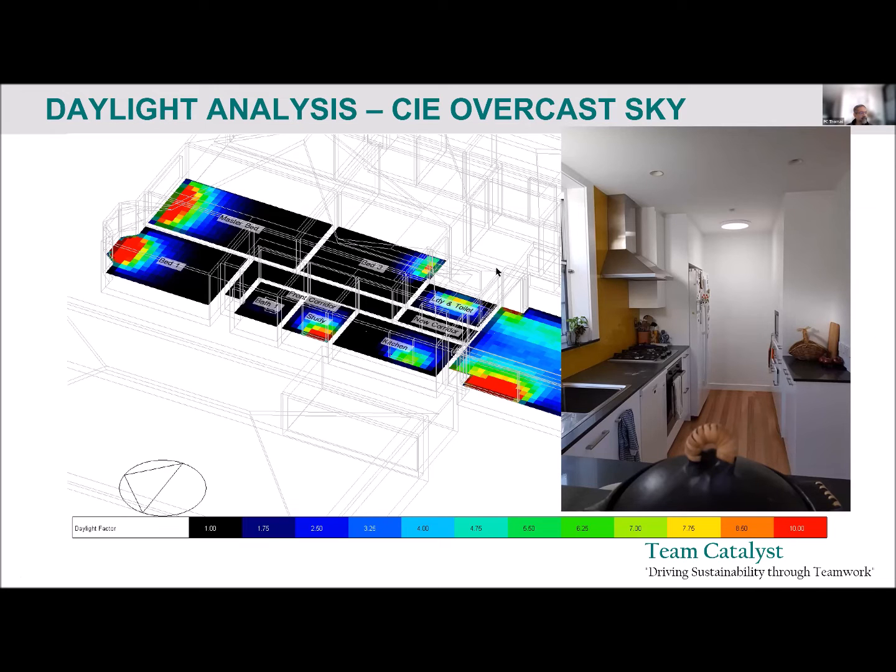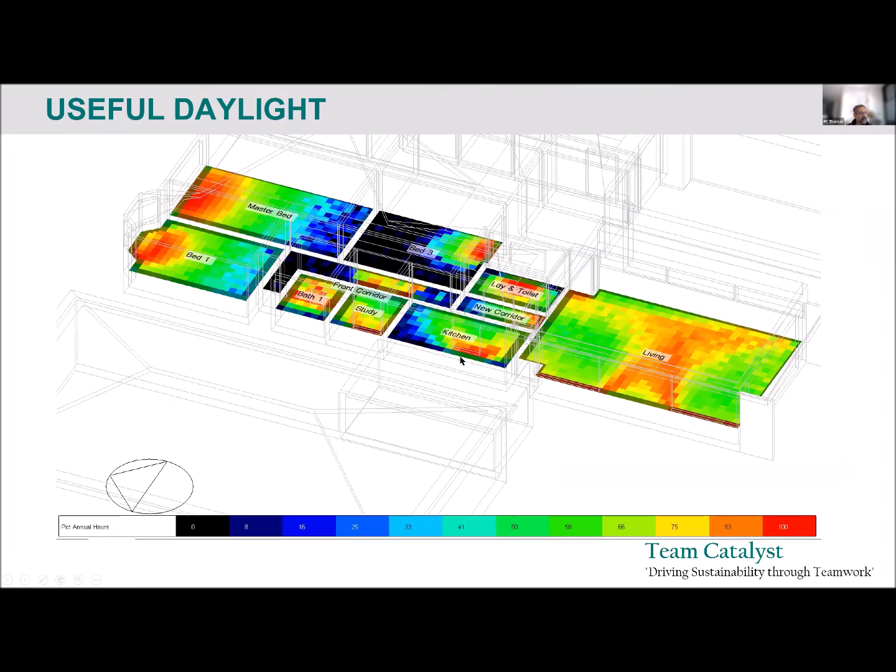Okay, here is another kind of daylighting analysis. This is an annual daylighting analysis. It's called UDI, the Useful Daylight Index, and that allows you to specify a minimum daylight factor or daylight level and the maximum daylight level. It crunches through every hour when daylight is available, and it tells you what percentage of the time daylight is within that limit. So it's neither too low nor too high. Too high means glare, too low means not enough light.